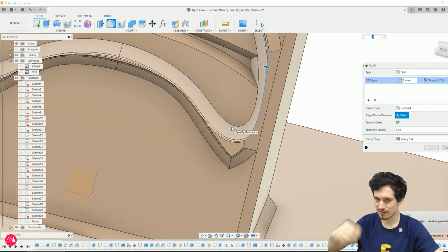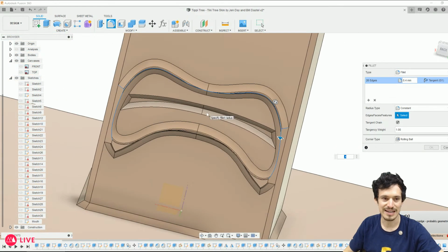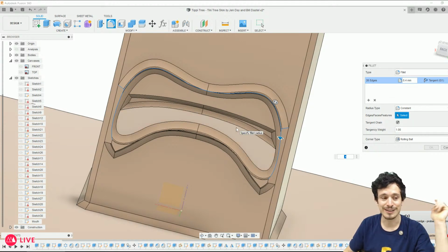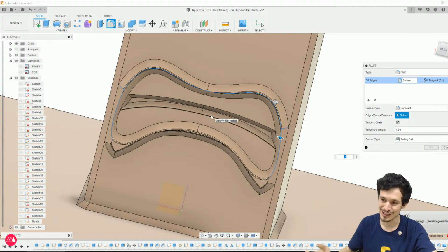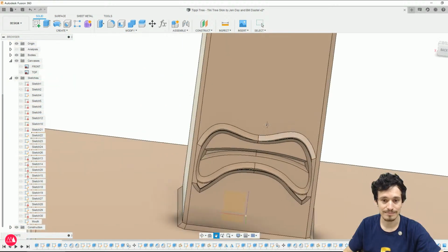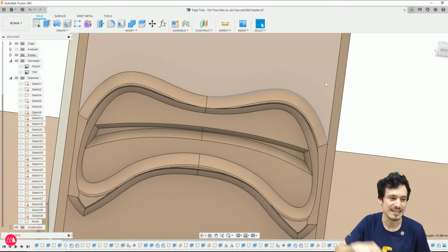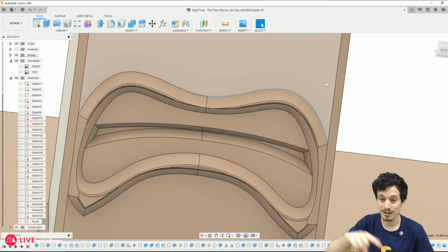James, would it be easier to do all of this in Illustrator? In some ways, yes. The spline tools and just general vector line tools are easier in Illustrator. For one thing, Illustrator is on my MacBook, so I can't stream it. So I'm partially doing it just because I wouldn't be able to stream it. But on top of that, just working within Fusion gives you a little more power. The lines are made in Fusion, so sometimes if you bring a DXF file in from Illustrator, a line will look like a circle, but it's actually just a curve with a dot. It won't let you actually import a true circle, and that breaks some of the functions within Fusion.